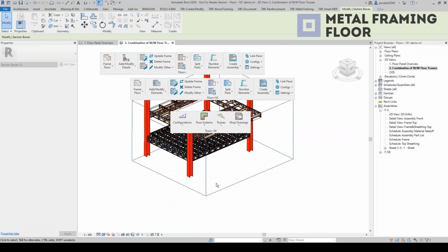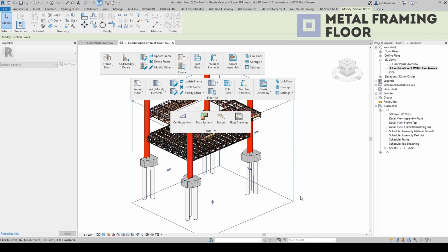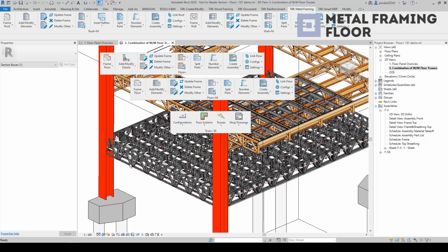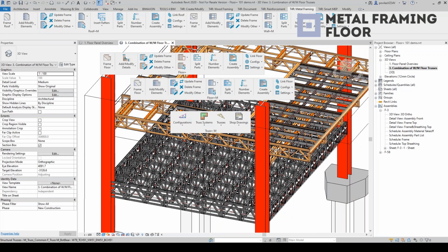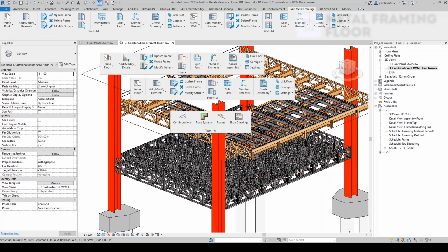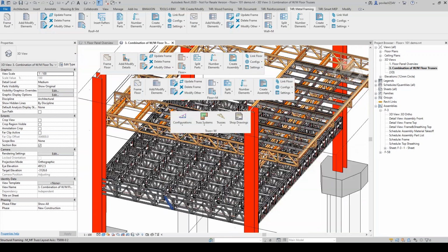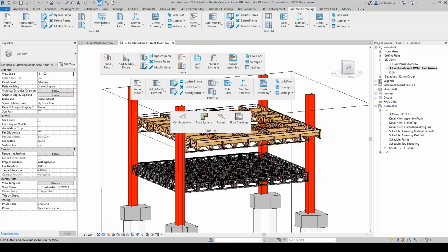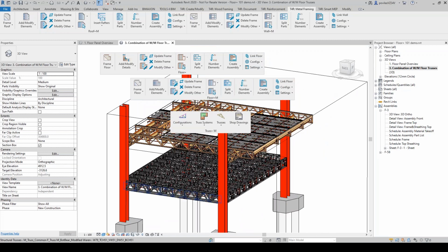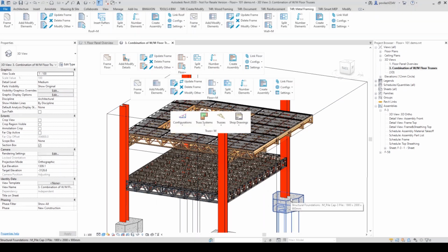okay, we see more context, and it's an instance of exactly the same workflow that was done producing the steel floor trusses. So again, you insert layout lines, and then upon those you build your trusses. The good thing about it is that you can set your layout lines, and then if changes happen, you can easily redefine your layout before you even have produced a single truss. And when the layout is set, you can then start framing.